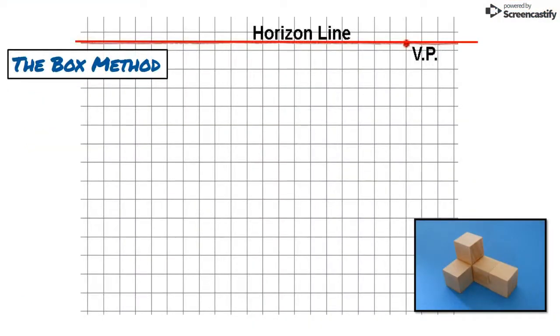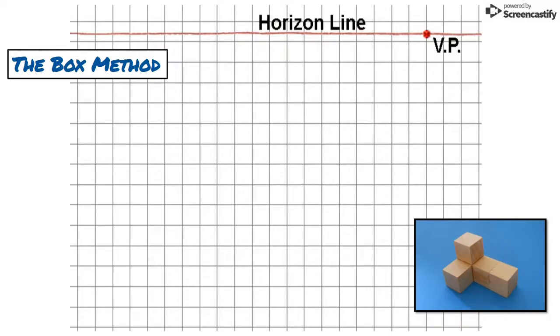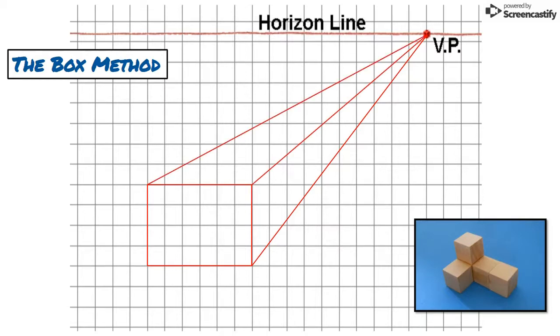First, sketch a horizontal line across the upper portion of the paper to represent the horizon, and identify a vanishing point. The vanishing point can be placed anywhere along the horizon line. Then, sketch the front face of a box, representing the overall size of the object. Next, sketch construction lines from the corners of the front face of the box back to the vanishing point. These construction lines are known as perspective lines. Now sketch the visible back edges of the box to represent the overall size of the object. Estimate the depth of the object to create proportions that produce a realistic appearance.